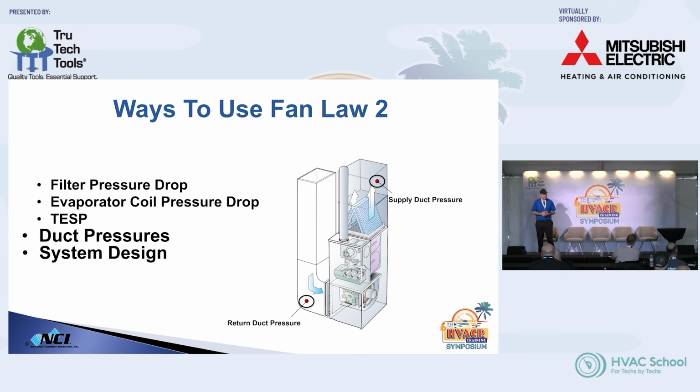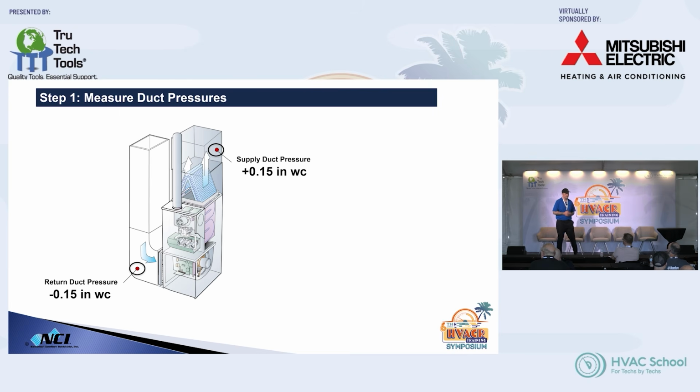So this next situation here, we're going to look at duct pressures. This really changed the way I looked at everything. And I would have to say that the situations where you would run into this are when you start replacing like-for-like equipment and you weren't planning for your pressure drops.